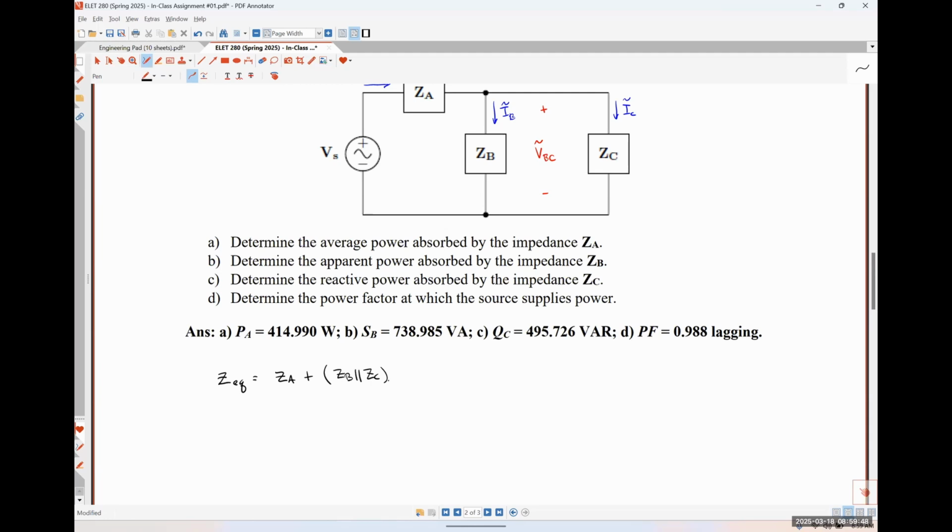So when you guys learned to do parallel combinations of elements, how did you learn how to do it? There's two, you can multiply on top and divide by the added one. Exactly. I just wanted to make sure that you knew the shorthand way to do it, because that's the way that I'm going to do it for sure. But you are correct that that only works whenever there's two elements.